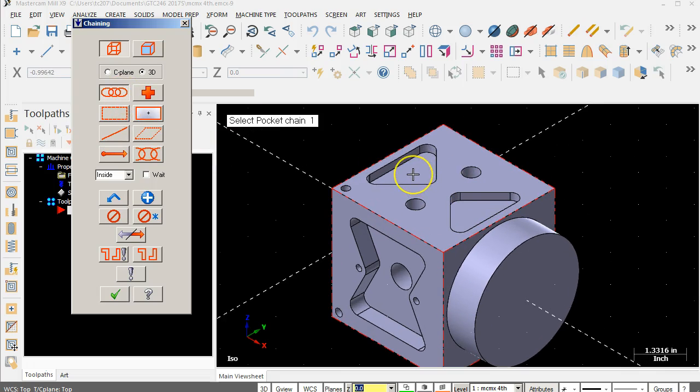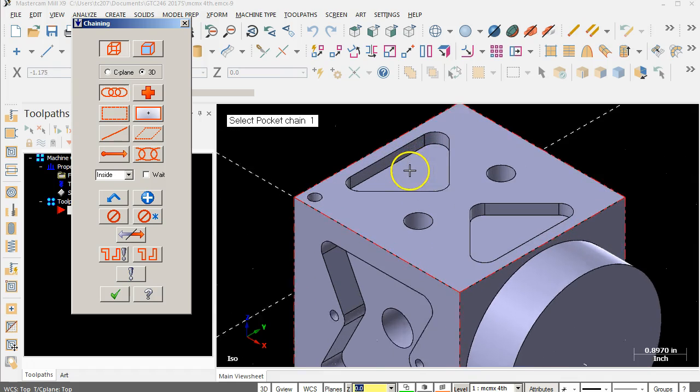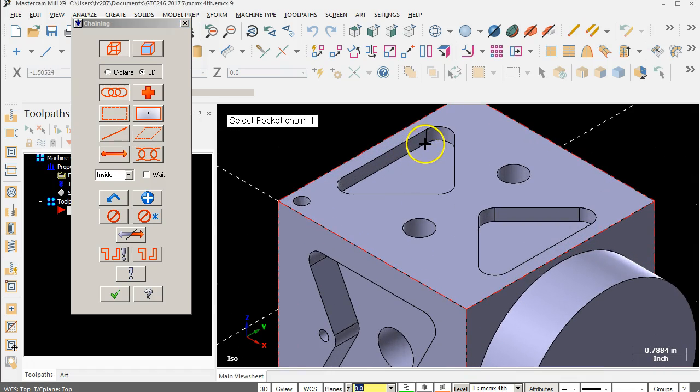settings. I also have to decide if I am going to use the incrementals. Right? I really don't want to calculate everything in absolute. So we all kind of struggle with the incremental settings, but it's really going to save us a lot of trouble here being able to set those depths, which are now going to be heights, because our 0, 0 is at the center of the part. So there's some things that are kind of counterintuitive and things that are just a pain.